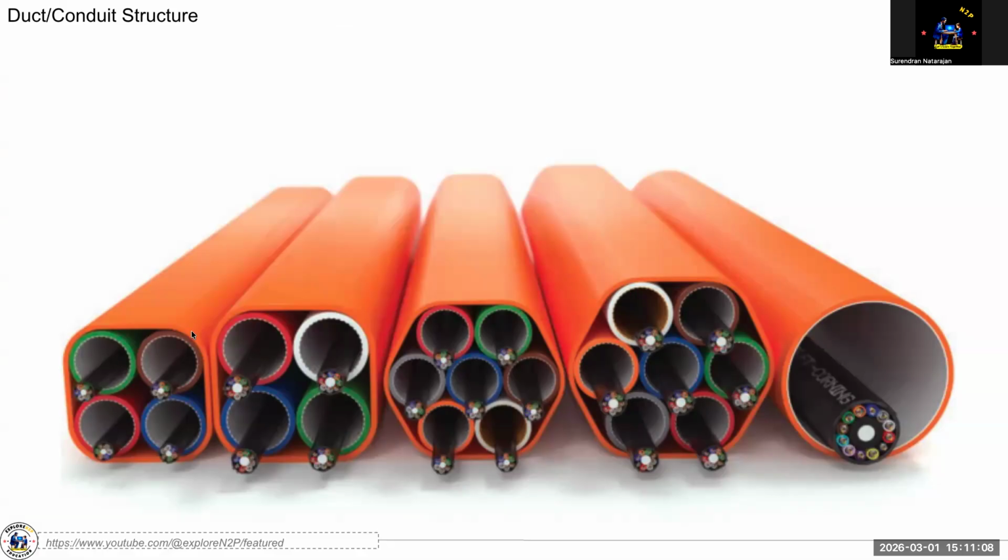See, this is the duct, one big duct here. Inside, there are four smaller ducts, each a duct inside a duct, and this is the actual fiber. How many fibers are there in this black cable? One, two, three, four, five, six. Six fibers. In the center, the white part is like thick plastic. It looks like another cable, but it is called a strengthening material. If it is not there, you will easily bend the cable and it will break, because it is glass.